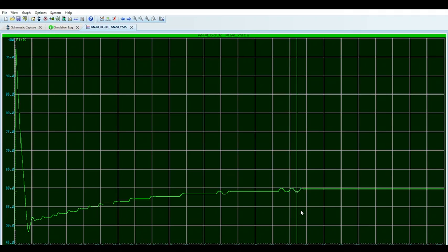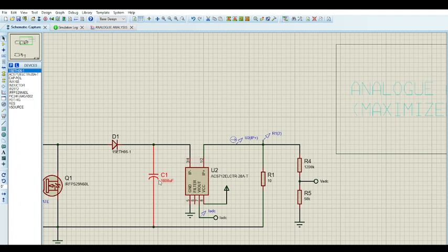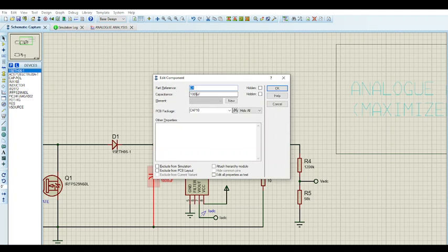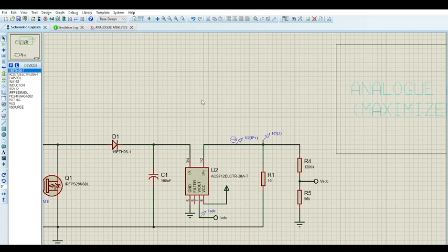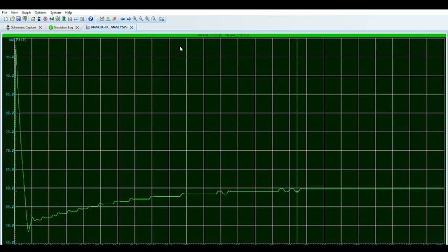But just remember, in the case of other converters such as a buck, they're very sensitive to the capacitor values, and it's much better to just have a smaller capacitance here. I promise you it's better, because I tested this on a buck converter and there were a lot of problems experienced because of that.